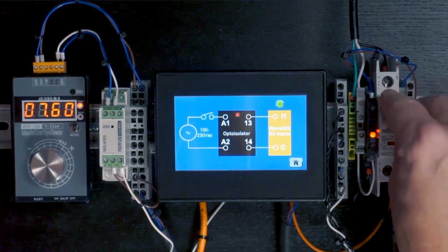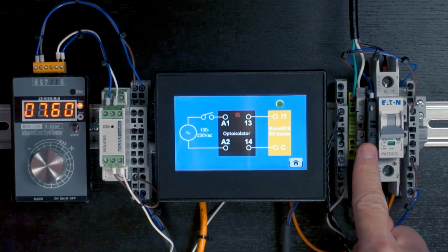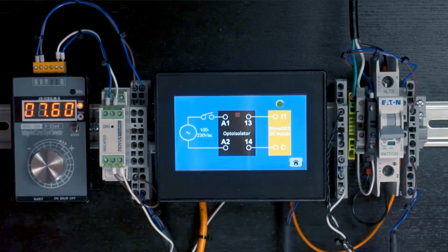Now the beauty of these devices is that you basically use 1 per AC input that you have. So if you've got, let's say, 3 AC inputs total in your system, you would use 3 of these Optoisolators, and they're not all that expensive, frankly, and then the rest of your inputs are still available for standard DC type inputs.